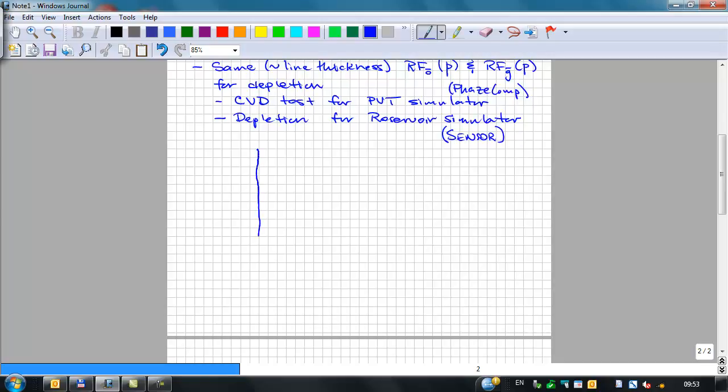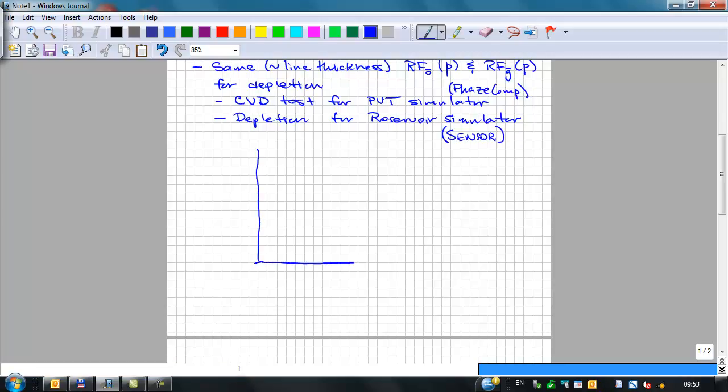I'll just sketch the graph. What we're going to be trying to create here is our recovery factor, which is defined as the oil produced or condensate produced over the initial oil in place, or the cumulative gas. That's processed surface gas, not wet gas or well stream, but actually sales gas divided by the initial amount of sales gas in place. That's a recovery factor from 0 to 100%.